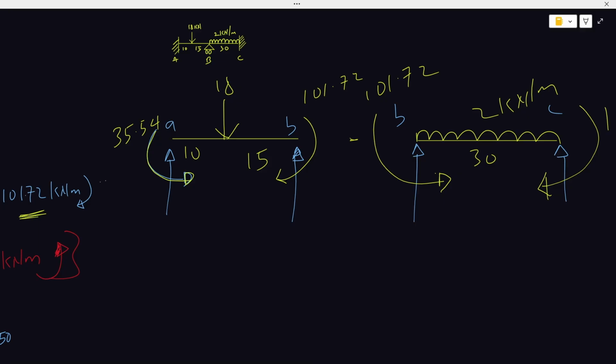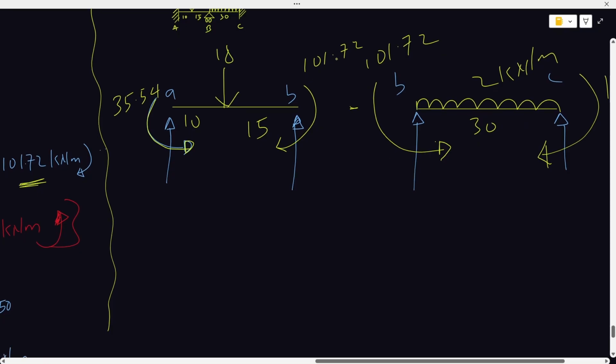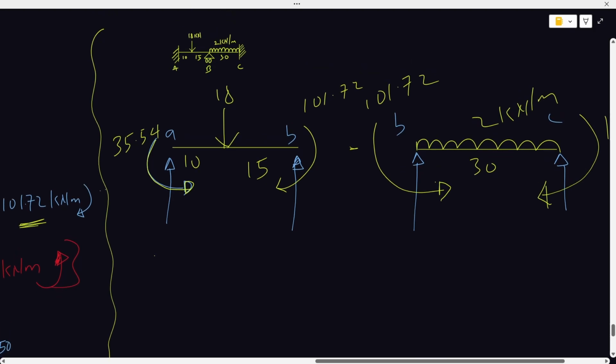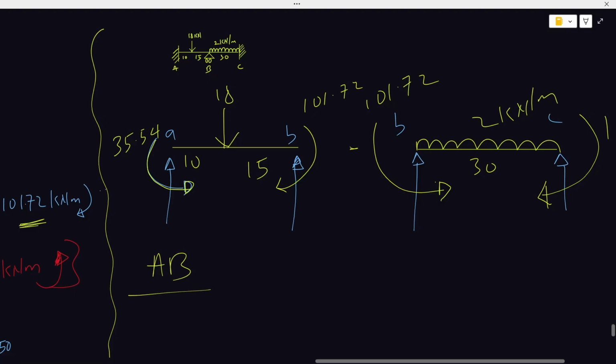So let's just have a boundary line. We'll be applying the equilibrium equation to each of the members, applying equilibrium equations to member AB first. Now, remember that I've gotten my member end moment, then I split my structure, then apply the member end moment to my structure where it is supposed to be.